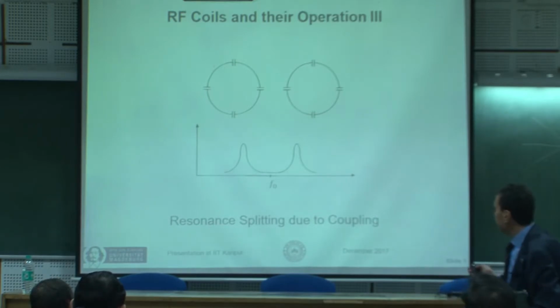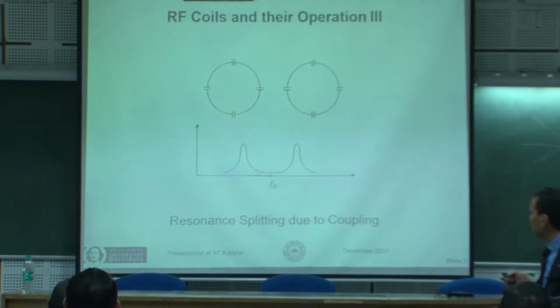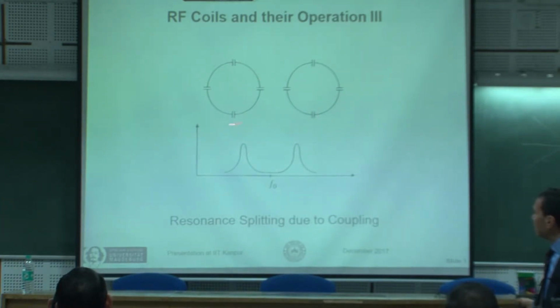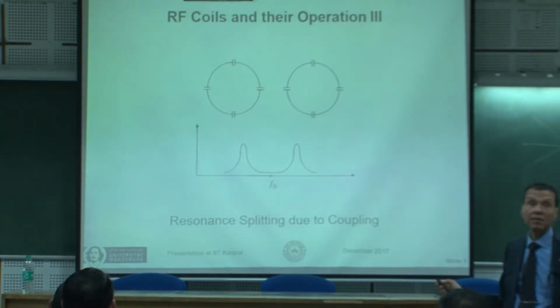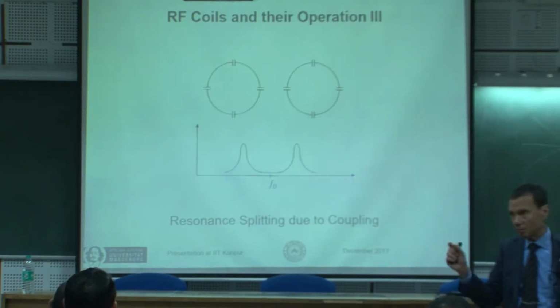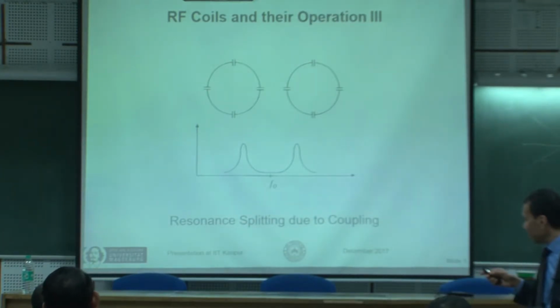Okay, again, I consider here two identical coils. Simply, the coils are equipped with capacitors in order to guarantee high resonance. And high resonance in the receiving scenario is also important for minimizing noise, because with high resonance, you pick up only the part of the noise within your band. Okay?